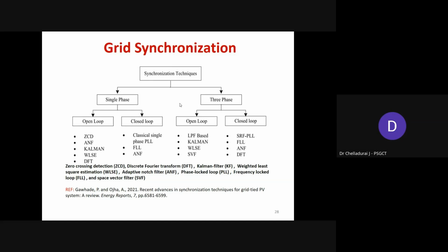But in the real-time power system network, mostly the grid is controlled with the help of these huge size alternators, whether through hydroelectric power generation or thermal or nuclear. Then, using renewable energy conversion, if you want to inject power into the power system network with the help of voltage source converters, initially the voltage source converter has to be connected with the help of the grid voltage reference.